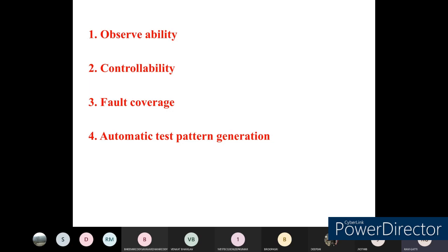Okay, so how do you identify this fault coverage? It is a circuit with no node artificially set to 0, meaning manually we are not going to set it to 0 or 1. If any discrepancy is detected between the fault machine, that is the finite state machine we have used, and the functional machine, the fault will be marked as detected and the simulation will be stopped.